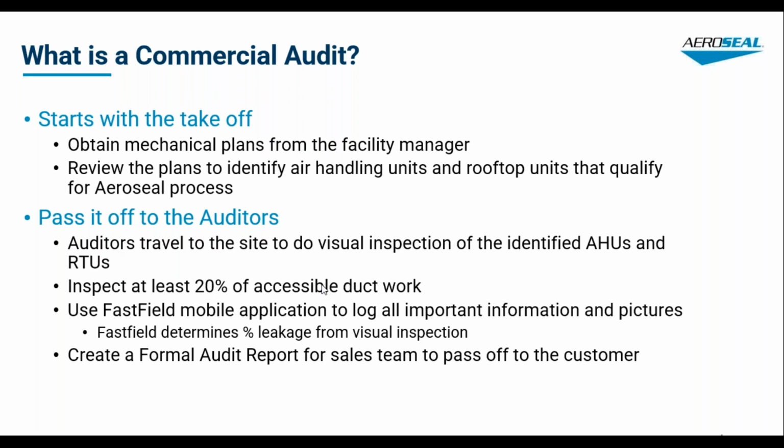We'll do a visual inspection of the identified air handlers and rooftop units, and we'll inspect at least 20% of the accessible ductwork. Then we'll use the FastField mobile app to log all the important information and pictures, and that determines the leakage per rooftop or air handling unit. And then we will create a formal audit report for the sales team to give to the customer.